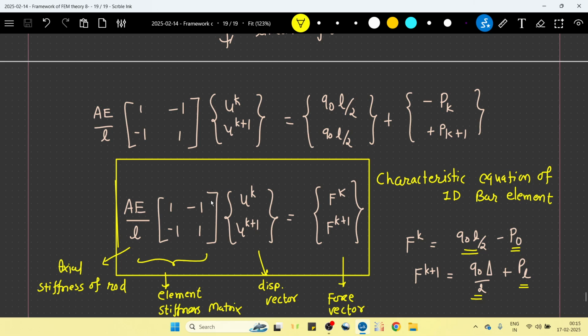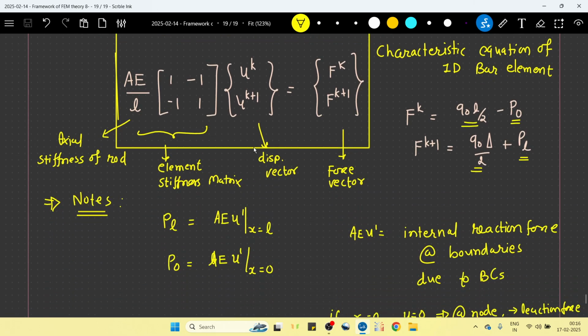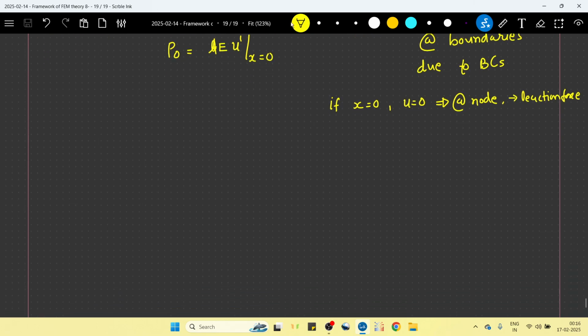And this particular equation is exactly the same equation we got in our first two videos of this series using the solid mechanics approach. There we just took a single element, so the displacement vector was U1 U2, and the force vector was F1 F2. So now we have understood clearly the final equations. We have got the FEA equation using the FEA method. Once we get element level equations, what next?